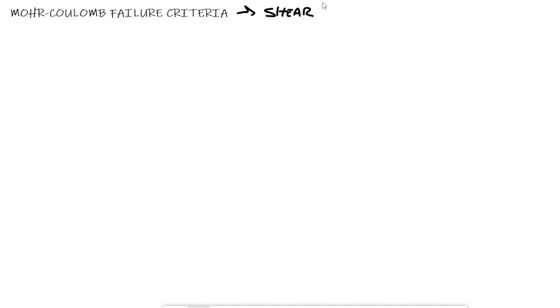Now, to give you the rundown, the review, Mohr-Coulomb or MC failure criteria is very nice. It's very nice because it's linear. Linear, of course, mathematically makes us breathe a bit of a sigh of relief. It's easy to set up, it's easy to use, it's easy to understand. It can be done completely analytically, no need for any numerical stuff going on. So it's linear, that's nice.